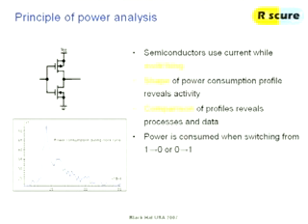The other one is power. So CPUs, and basically every electronic equipment these days, is built up of gates. And gates switch. They switch between ones and zeros and back. And when they do that, they consume power. They consume power because they have leak currents. They consume power because they have to charge and discharge capacitors. Once a clock is switching, at that moment that the clock switches, all these gates become active. And they become active in a kind of an avalanche process until they're all done.